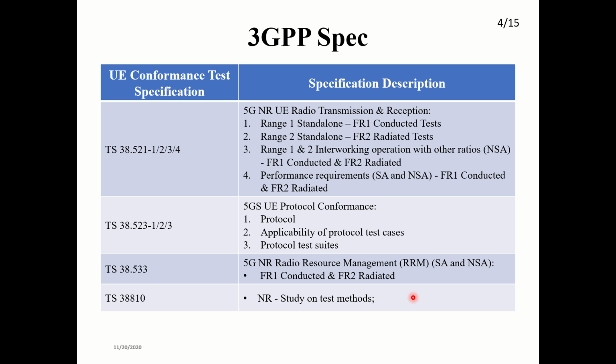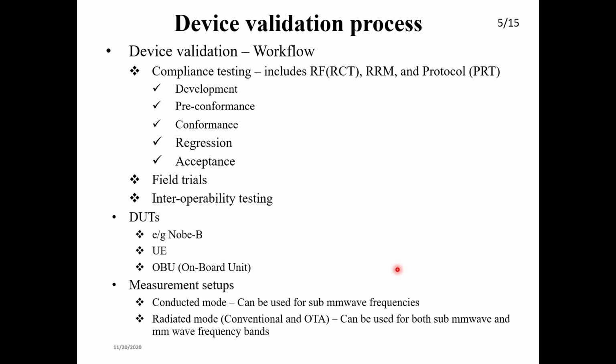Like for EMC, for example, some of the products get standardized. For example, FCC, IEC, and there are civilian standards and military standards. Some other standards are available too. If you want to sell your product to the military, you need to follow those. You need to comply with IEC and FCC, and those kinds of military standards are available. There they will mention each and everything: what components are to be there, how it should be measured, and many other things will be mentioned there.